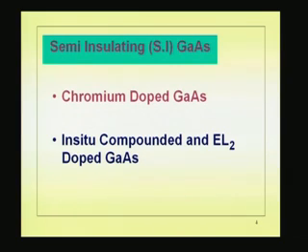And silicon, you know, in gallium arsenide is an N-type dopant. So, when you grow by the Czochralski technique, usually from a melt prepared from polycrystalline gallium arsenide, first you prepare a polycrystalline material, and then use it as a melt and pull the crystal, that turns out to be N-type because of the silicon. And you will say undoped gallium arsenide, carrier concentration 10 to the power of 15. That sounds funny, because you say undoped, but the carrier concentration is 10 to the power of 15.